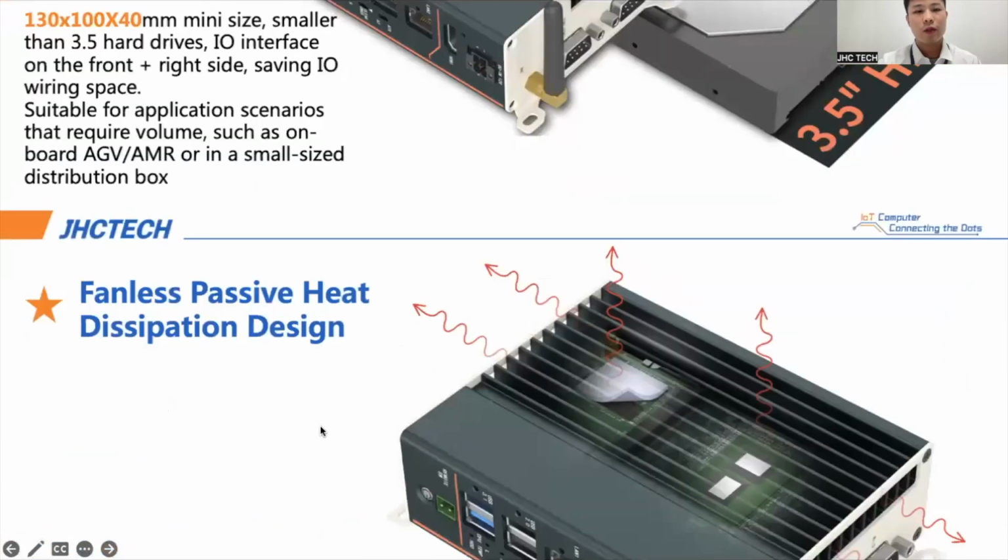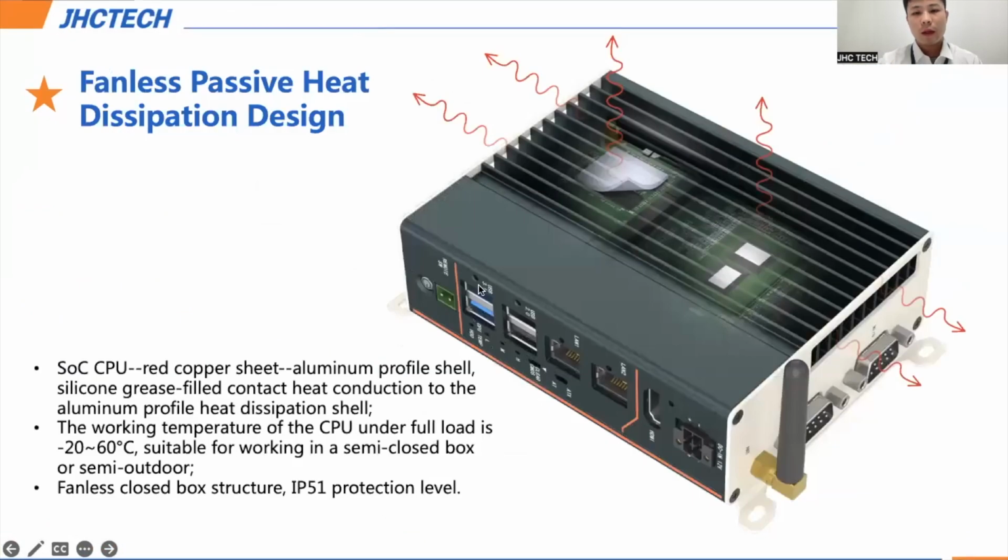Okay, next page. It's a fanless box computer with IP51 protection level. For CPU cooling, it adopts a passive heat dissipation design. So it can support a wide working temperature, suitable for working in a semi-closed box or semi-outdoor applications.